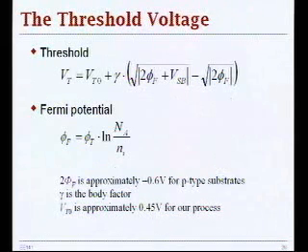And as you remember from your device class, you have your basic threshold voltage defined as VT0, where you have no bias at your bulk terminal, and then you have this correction term for body bias. This is a body effect factor gamma here that describes the impact of biasing your body terminal relative to the source on your threshold voltage.